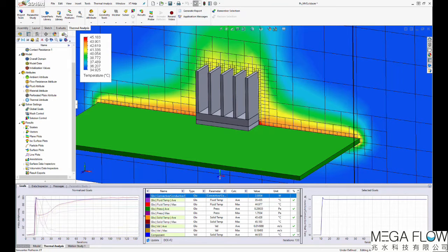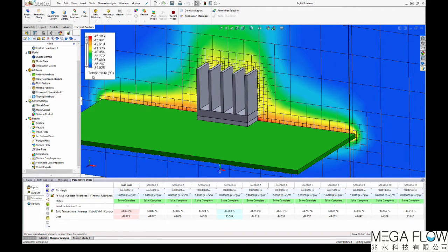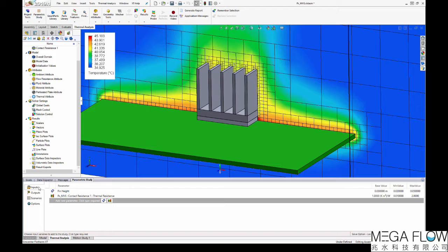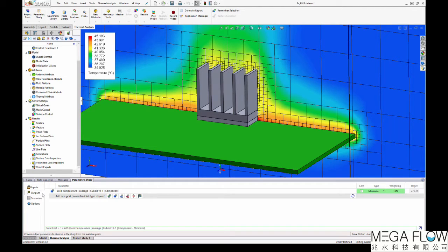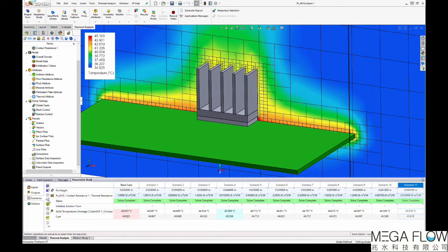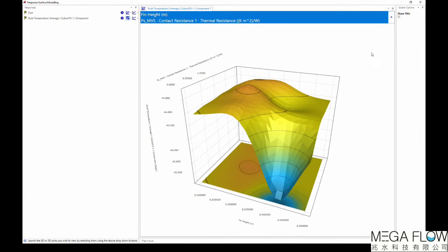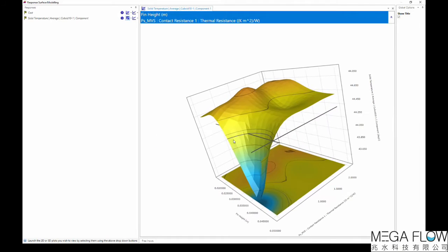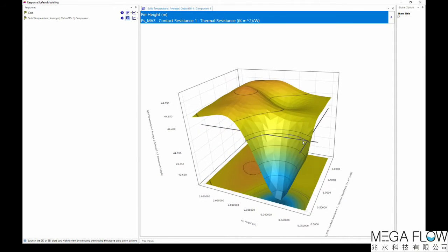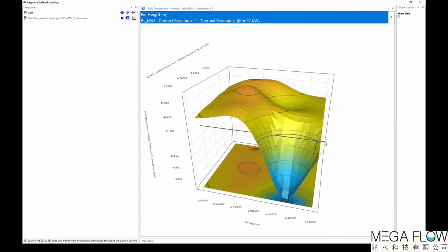Alternatively, DOE can be used. In this instance, a user will simply define the minimum and maximum range for two or more parameters, define the number of scenarios to create, and the software will automatically fill in data to create the best coverage of a design space. A cost function can be added to drive the software towards an optimum, and response surface modelling can be utilised to numerically predict the results in the gaps. While this is a tried and tested method, the downside is that you may need a large number of experiments to accurately fill the design space and obtain sufficient resolution in the response surface.